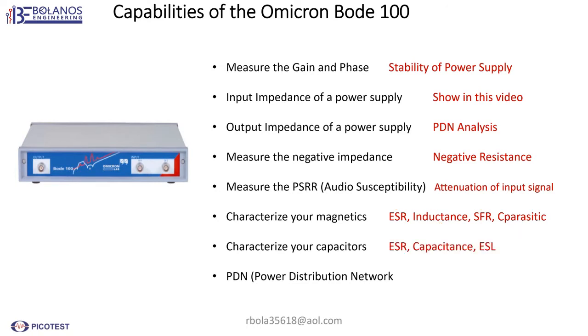Okay, here is another task that you can do: characterize your capacitors. On your capacitors, you can measure the ESR, you can measure the capacitance, and then you can also measure your ESL, which is the equivalent series inductance. Very important.